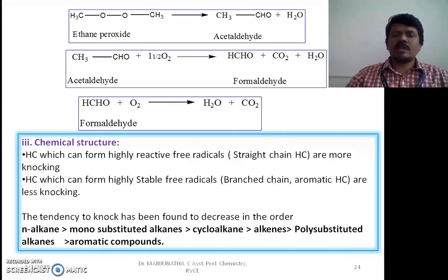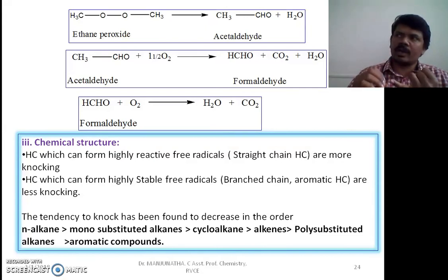Okay. So knocking is a metallic sound which is produced in an IC engine due to uneven combustion of the fuel and air mixture. This is because of three reasons. Pre-ignition: if the CR value crosses a certain specified value, the fuel and air mixture suddenly catches fire before the spark is produced from the spark plug. That is one reason. The second reason is self-ignition.